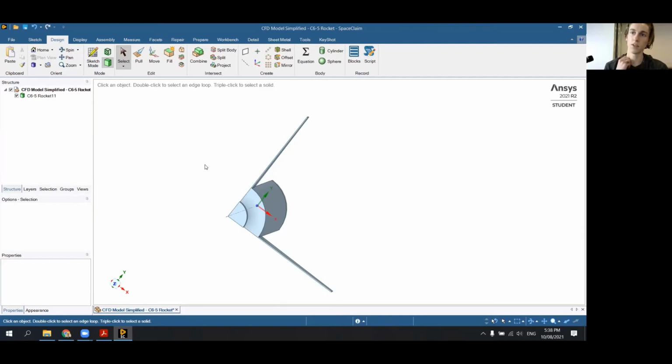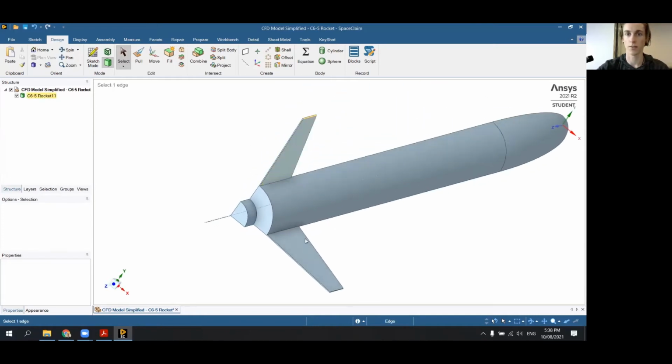The symmetry boundary condition would be at a different point because we've specified that the flow should be symmetric around these 2 fins. So it would allow you to get some asymmetric flow around your fin, but it wouldn't affect the results significantly if you did everything the same. And it would probably make your enclosure a little bit simpler because you just have the 1 fin. So that's an option. It's definitely an option, and it wouldn't change the results too much. I'll have to try it. Thanks.